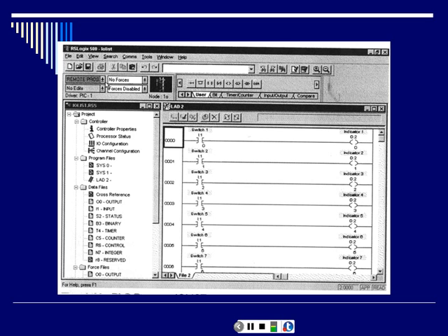But notice all the switches look the same. They're all contacts. And that's all we look at them as. That's why we've got to name them, push button or switch or whatever. All the outputs are the same. It doesn't matter if it's a light or a motor or a bell or a buzzer or a solenoid. It's all a circle. There are a few other outputs.